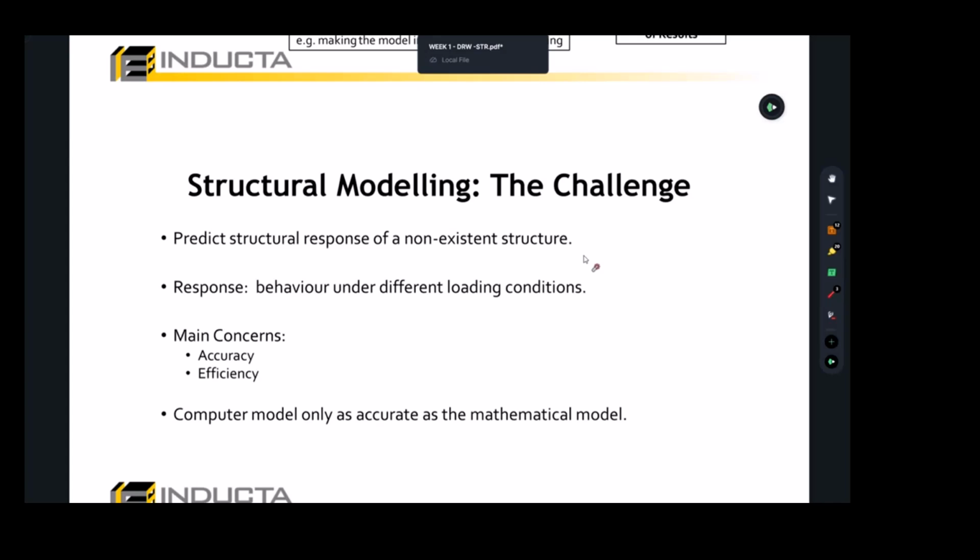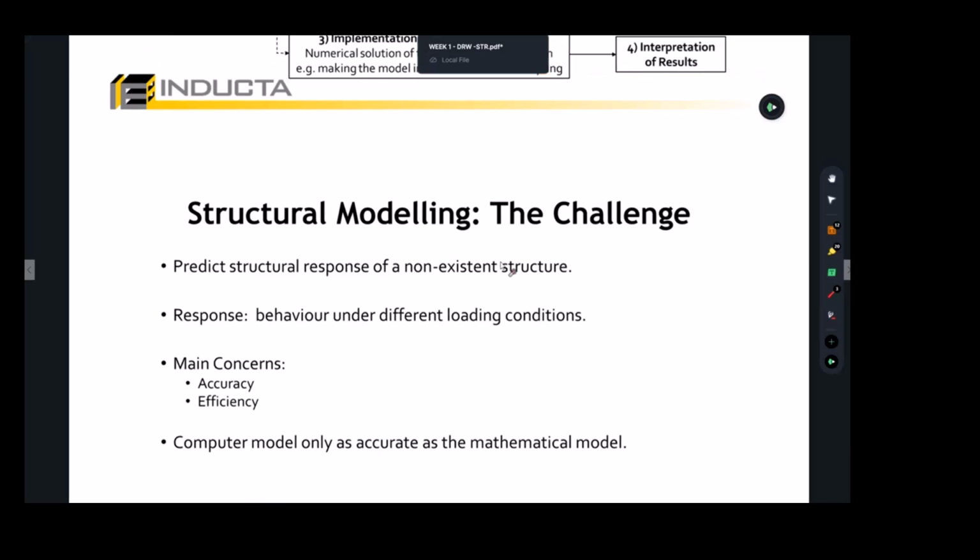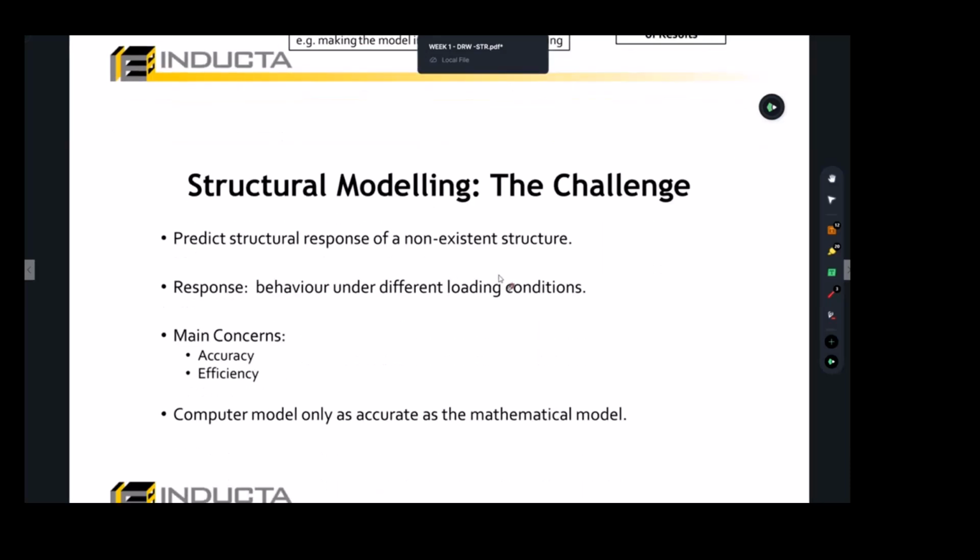You need to switch on that imagination side of your engineering skills. There are no equations or step-by-step guidelines to let you do this. Sometimes some of the steps may be bypassed in one project, but you have to go through them in another project. For example, if your core was in the center in a project, you can follow steps. However, if it was excessively located at a corner in your building, you have to go through a different process, right? And then if the core itself was symmetrical, it's different than if it was not symmetrical.